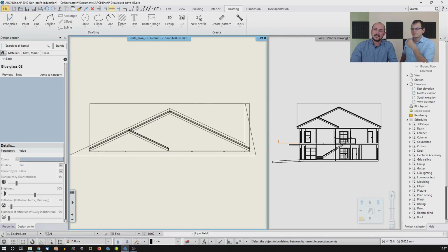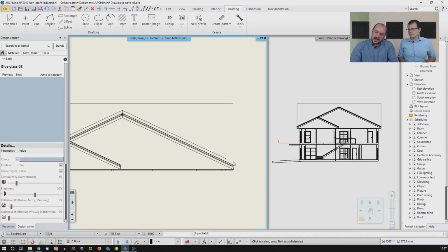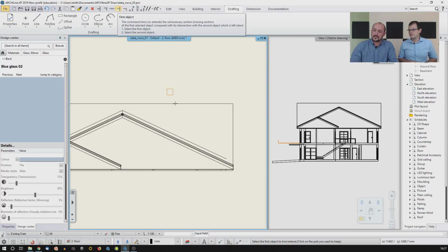I use it to clear up my design from time to time and just make sure that I get rid of those tiny unwanted parts. I just chop them off. And then if this line should meet with the other one, should be joined together, then this is when you will use a T-connection, but not with the walls, but with the lines or the 2D items. So I just use this here and I just join them together.